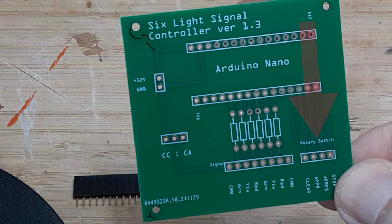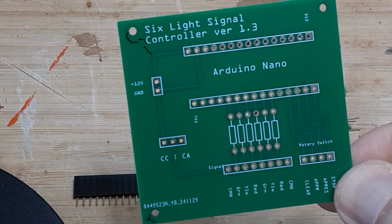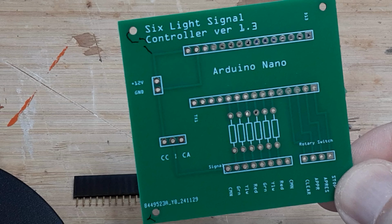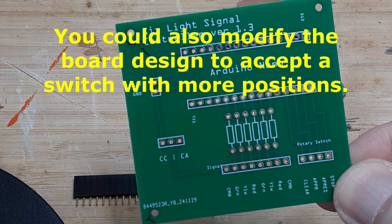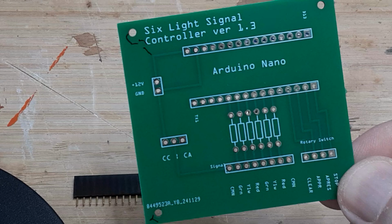It has 4 input connections, allowing selection of up to 4 aspects using a 4-position switch, or 6 aspects using a 3-position switch and an auxiliary switch machine contact, or up to 16 aspects by using up to 4 toggle switches to input the numeric value of the aspect.